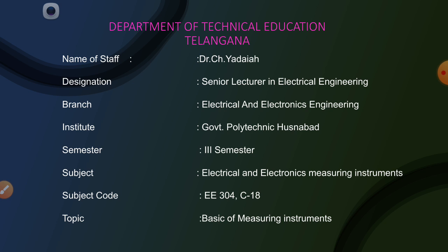Now, after completion of the controlling torque, we want to avoid the oscillations at the final position. For that purpose the damping torque is required. It is necessary to avoid the oscillations of the moving system about its final deflection. So we require the damping torque. The damping torque can be produced in our instruments by using air friction damping, fluid friction damping, and eddy current damping.